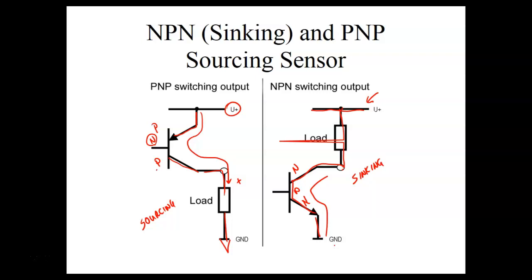So that's how these things got the name. I'm guessing that's going to be common on a photocell and a light bulb, like on your garage with a photocell. That's kind of how that works, right? If it's hooked up to 120, NPN and PNP transistors don't work with AC, they work with DC. Later on, we'll look at a device called a triac, which basically does the same thing, but it'll switch AC. So normally, when your light is hooked up to 120 volts AC, we know we're not using NPN or PNP because these work off DC.